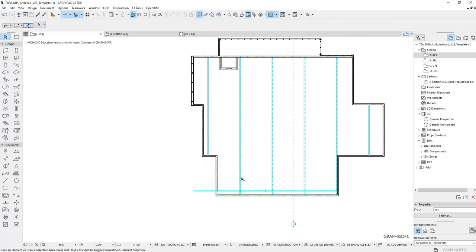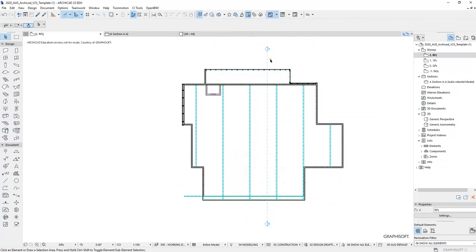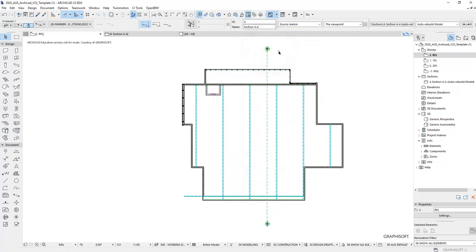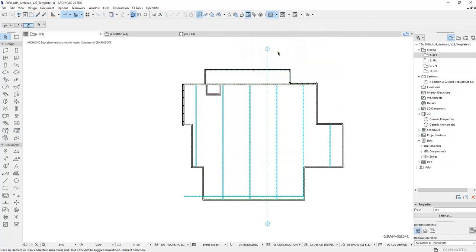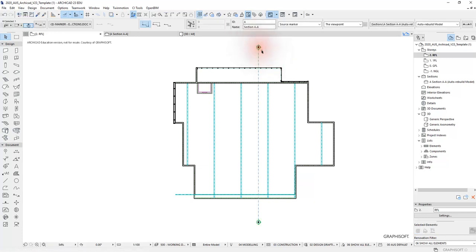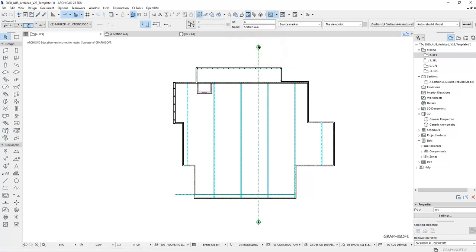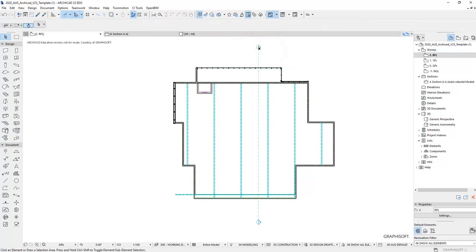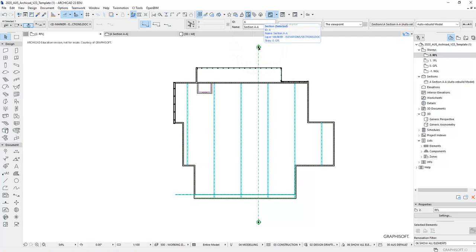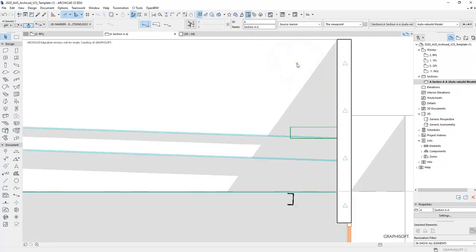Okay, right, so is my C channel sitting at the right spot, at the right height? I don't know. Let's check it out. So let's go to your section view. You can now go into a section view or elevation view. I mean, I can show you at least 3 different ways or 4 different ways to get there. So what I like to do, sometimes or most of the time, is by clicking on the section marker and then right click and then go open with current view settings, and it will bring me there.